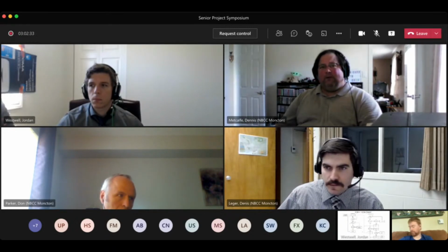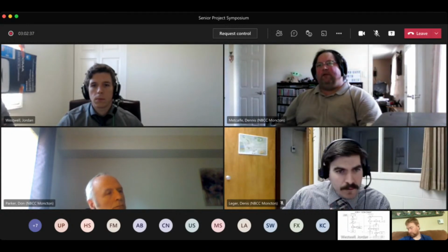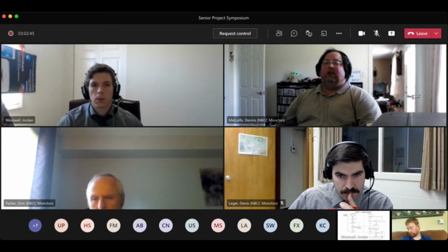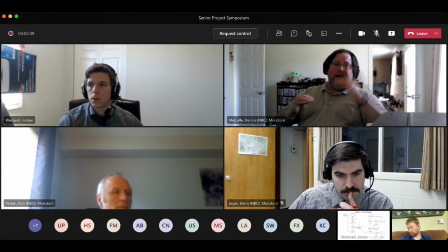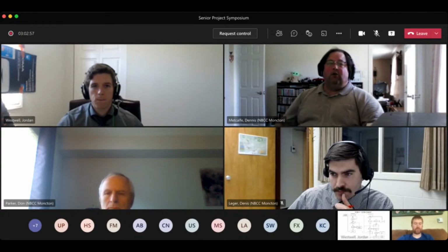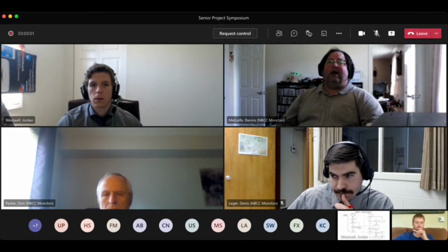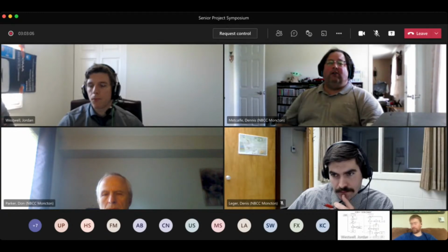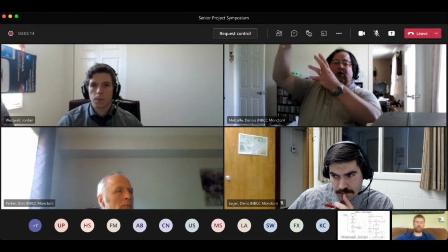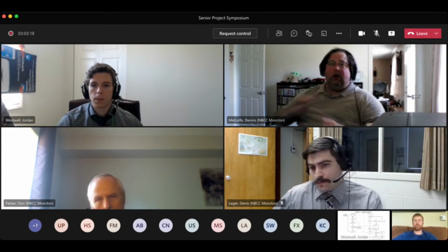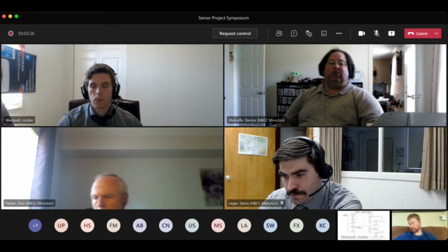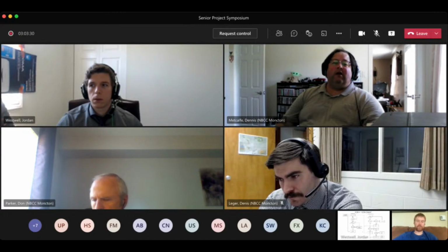My other comment for the flow chart is that you're showing the interrupt function as a separate thing, which is great, but you're always showing the interrupt returning to that first part in the main function. And that's not really true. An interrupt, when it occurs, can occur at any time, but when it returns, it always returns to the next line where it left off. So in that case, don't show an actual flow line going back to your main function. All you have to do is show an area where it says return or something like that, and just have the interrupt as a single flow chart of its own on the side. With all the logic you have, you've got great logic there. It's just that you keep showing that the interrupt will return to the start of the main function, which is not true. It will return to where it left off.